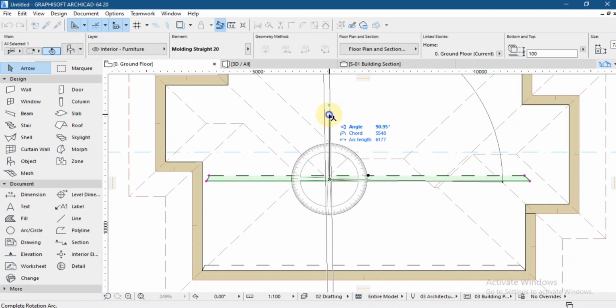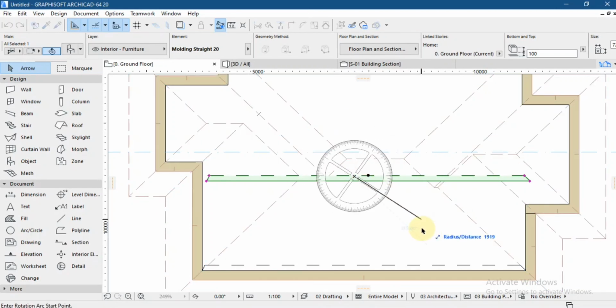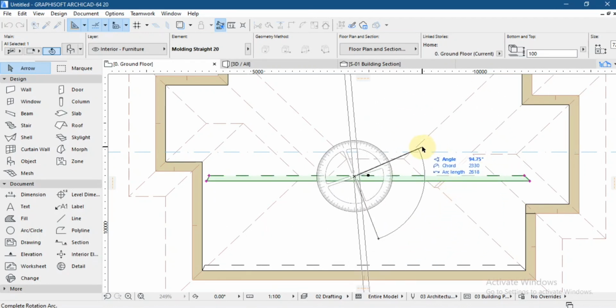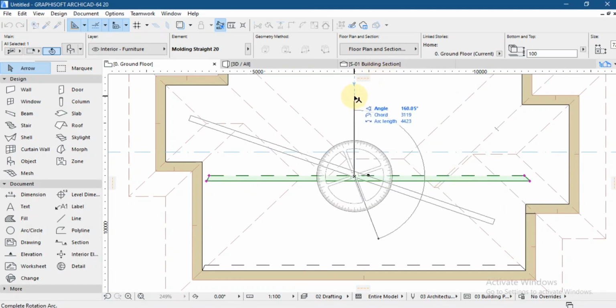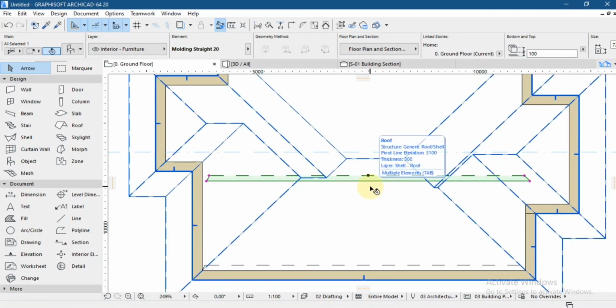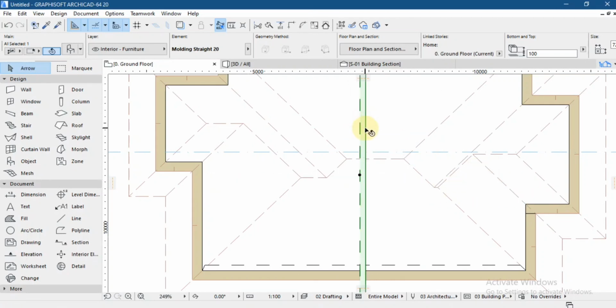This is the mistake if you pick a wrong line. If I were to pick this as my reference point, you see it rotates about this axis, meaning that it will be hard to get it straight. Meaning that when I have it straight here, it won't be straight. You understand? When I have it straight here, it won't be straight. Because that's the axis I picked. So it's good you pick the correct axis. So it will be straight when you rotate it.